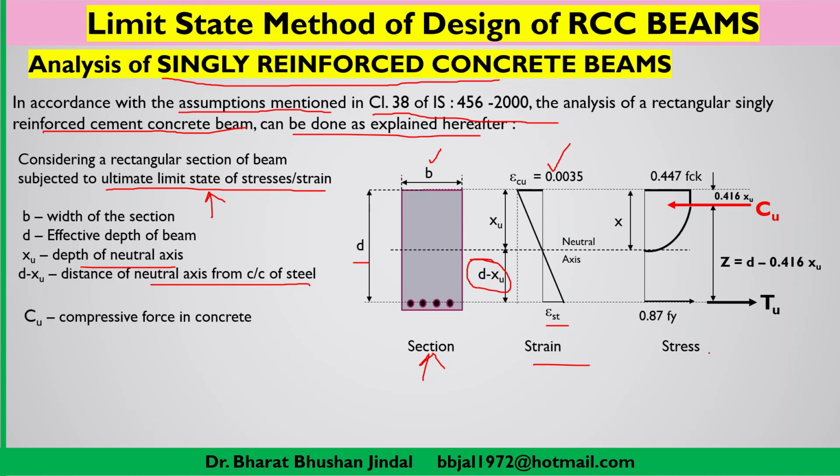Now when we draw the stress diagram as per the theory which we have already discussed, you can easily see here above the neutral axis compressive stresses can be seen. So this is the stress block for concrete, and as per the assumption which we have taken, below the neutral axis we are not showing any compressive stresses. So we are ignoring the compressive stresses taken by concrete, and only tensile stresses are taken care of by steel.